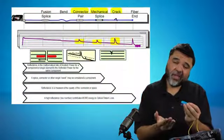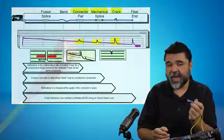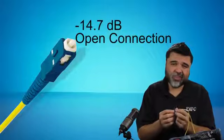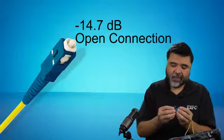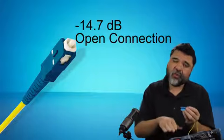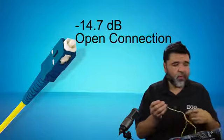The second value is reflection, or the percentage of light being returned. If I were to take a UPC connector or a flat cleaved fiber, apply a source to it, and measure the reflection, I expect to see about minus 14.7 dB of reflection. And so that is an open, just to give you an idea. And so the higher the number, the less reflection you have. Disregard the negative. So if you disregard the negative, the higher the number, the less reflection that you have coming back from that connector.